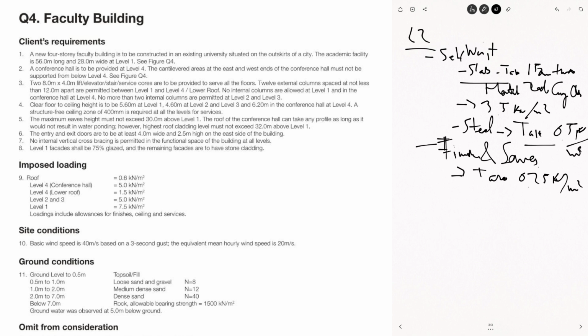It's just a normal way. Those values are normally shown in, for example, the structural engineer pocketbook. Take the 0.5 kilonewtons per square meter or 0.25 for finishes and services. So long as they are reasonable values, then you can just say that you're taking those values for this example.